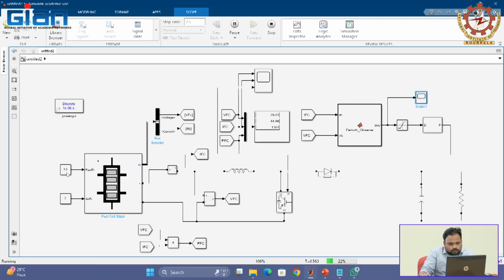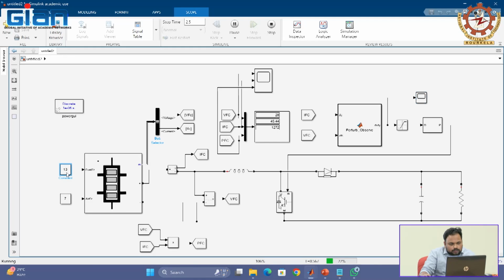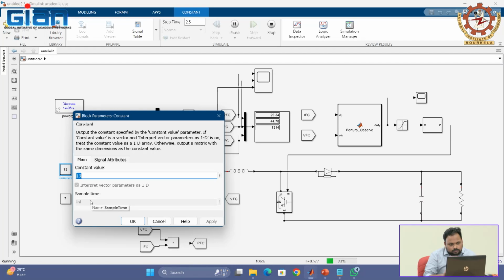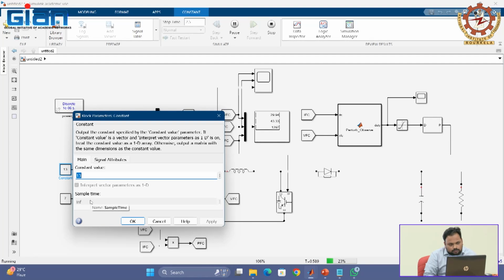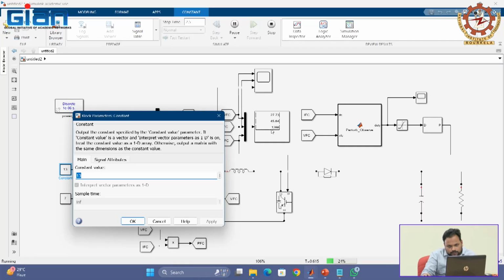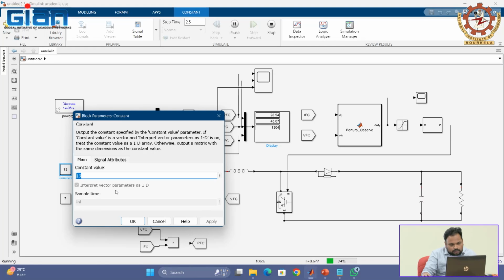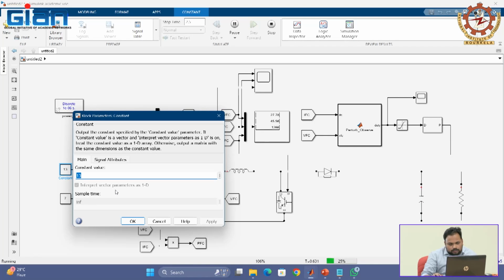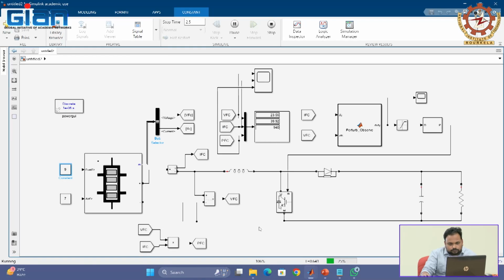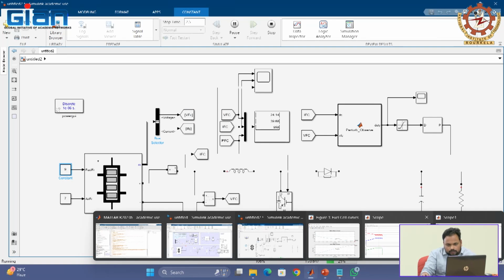If you change the fuel flow now, the power will drastically reduce. To demonstrate that, the current fuel flow is at 13 liters per minute, and the fuel cell is giving 1300 watts of power. Now I am reducing it to 9 liters per minute, and let's see what happens. Let's see the duty cycle.